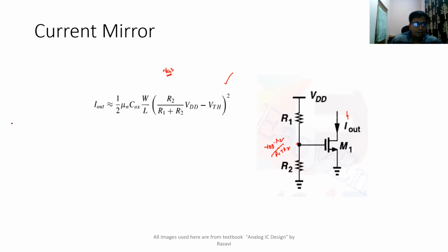This current source, whatever you generate, is a really, really bad current source. Why is it a very bad current source? What is a current source actually? What is a good current source? A good current source is one whose Iout value, whatever its current value, should be independent, first of all, of the voltage across its ends, V0. It needs to be independent of the voltage across it.